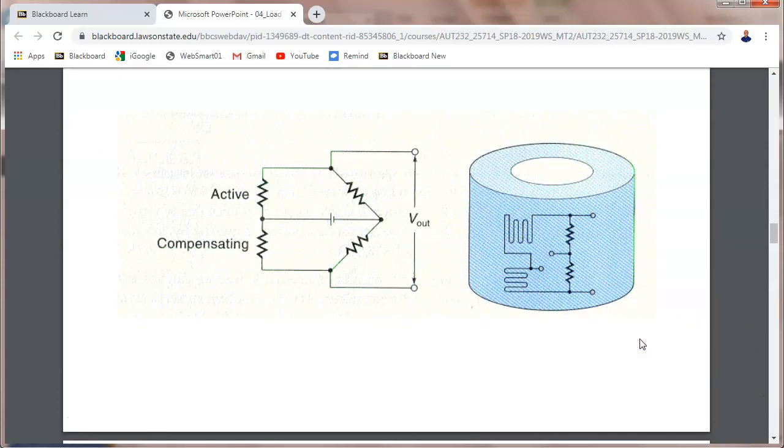So we'd have something. The big truck scales. These were, I can't remember the weight, like 50,000 pound scales. We had some 100,000 pound load cells that measured rail. These were on our railroad that measured trains, and then you put them one on each corner, which would give you 400,000 pounds that you could measure on the scale because it would be balanced out between the four sides.